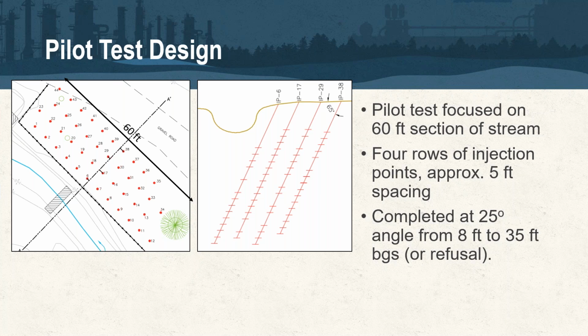And that's going to be a function of the geology, starting depth below grade. Because as your injection spacing widens, your injectate volume has to increase accordingly to meet the radius of influence that you need to match up with the adjacent location. So when you're working at, say, 5 feet below grade and you're at an active gas station, for example, because gas stations are good examples because they've usually had historic digs. They've had a lot of investigation work. There's tanks, obviously dispensers. And so there's a lot of things to work around.